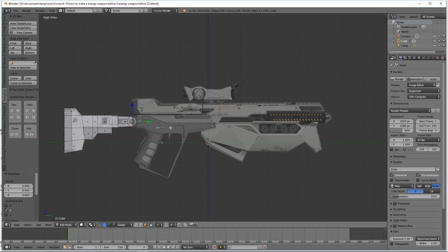What I'm going to do here is press E to extrude, then right click to get that geometry to stay in place. I'm going to press S to scale. I'm then going to left click. So when I scaled, basically, I scaled on every angle. And I was looking as this went up towards this angle right here. Basically what I'm doing is looking at ways that I can pull the geometry out and make this fairly simple.